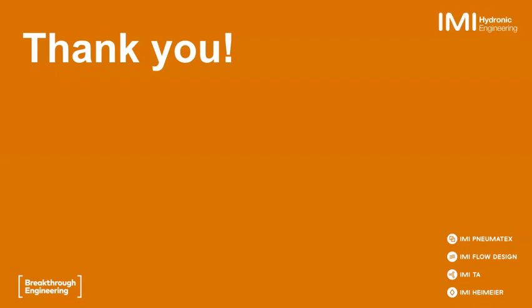All right. What percent energy savings have you seen by balancing HVAC systems? Yes, we even have a number here in the company that we use to promote. When you do a proper balancing and you're saving energy from the pump by optimizing it, you can save easily up to 30% of pumping energy. Okay, it's not the total HVAC energy, but from the pump you can save up to 30%.